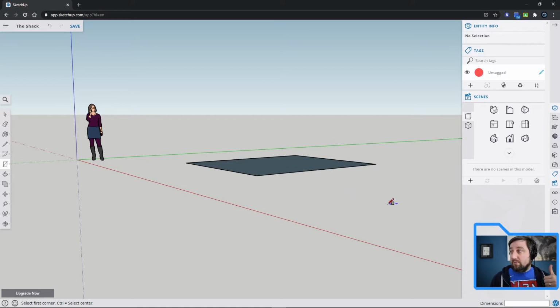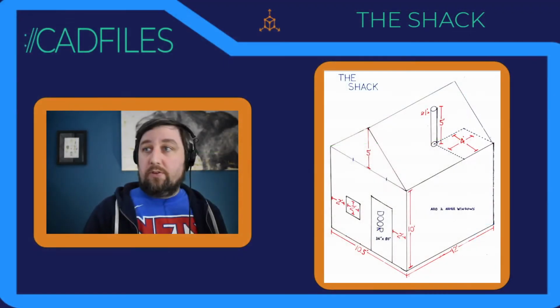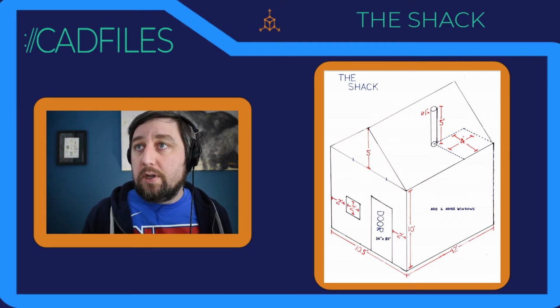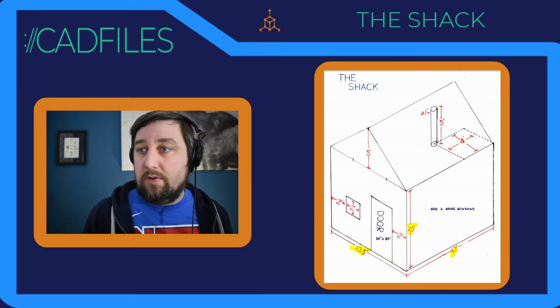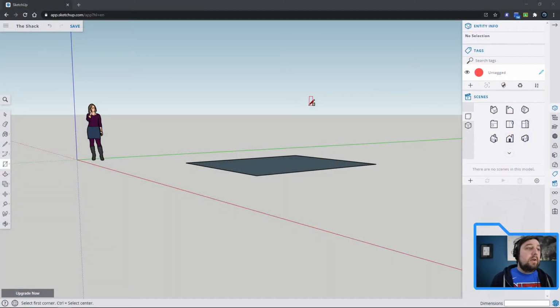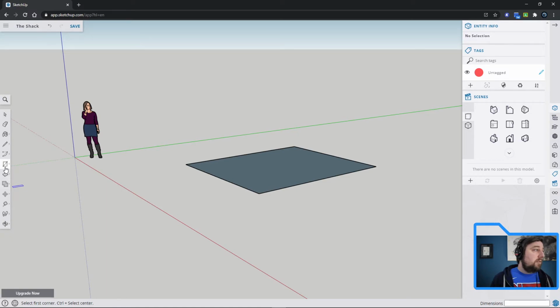Next thing, we want to make this 3D. I want to pull this up. So if I'm looking at my sheet again, how far up does this go? I only want to go up this area here of 10 feet, right? We did the 10.5 by 12, and I'm going to pull it up 10 feet. All right, so I'm going to go back here. I'm going to orbit around a little bit. I'm still in the rectangle tool. I don't want to be.